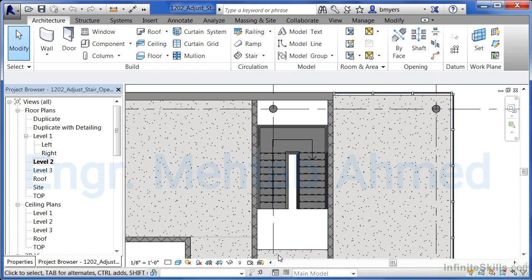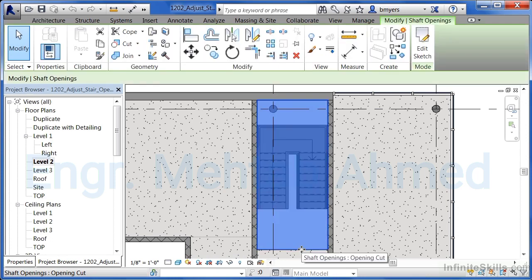In fact, we want the edge of our floor to be right up here, right at the edge of the staircase, so you can make the smooth transition from the landing, down the staircase, down to the lower level. To do that, we need to highlight on the edge of the opening. When you click on it, it'll all turn blue. Then come up to Edit Sketch.